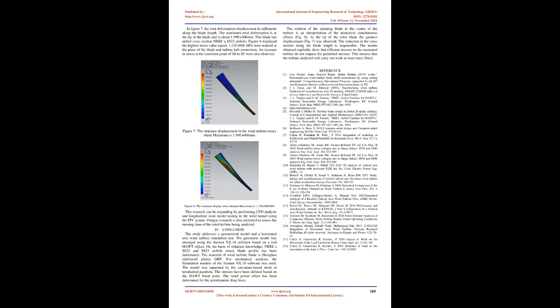which, after using the appropriate Siemens NX 10.0 tools, provide a full description of mechanical phenomena in the analyzed horizontal wind turbine. Simulation tests included static and dynamic analysis of the tested structure. In static analysis it was assumed that the model, Fig. 5, was affected by the force of gravity and centrifugal force caused by the blade's rotation. The wind force was also taken into account in accordance with Formula 1.